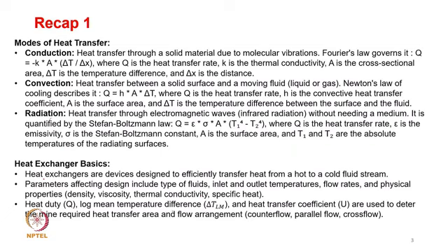The next important variables that we have learned are the heat duty, the logarithmic mean temperature difference and the heat transfer coefficient, which are used to determine the total heat transfer area, and the type of flow arrangement, which is the required flow, such as cross flow, counter flow, and parallel flow, and so on and so forth.